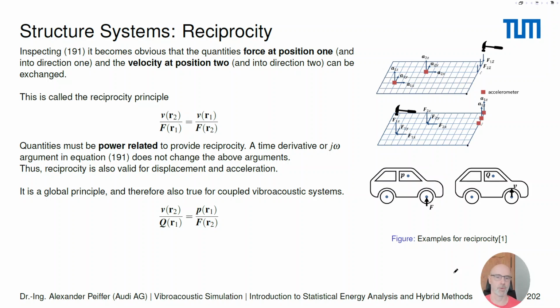Now we have to talk about another fact that is very important in acoustics and vibroacoustics, the principle of reciprocity. When you inspect the equations before, you can see that the force at one position and the velocity at the other position can be exchanged.